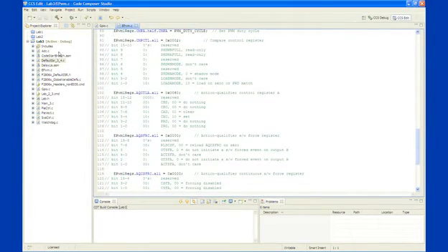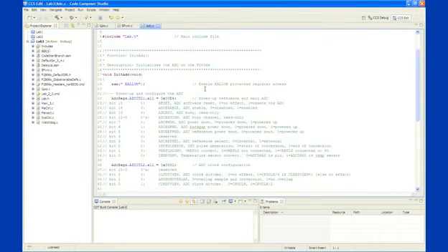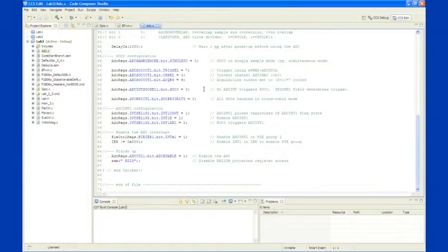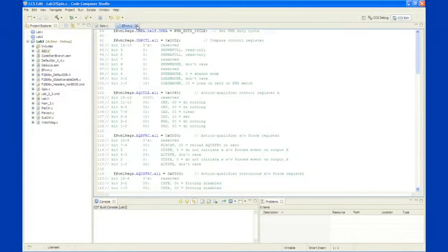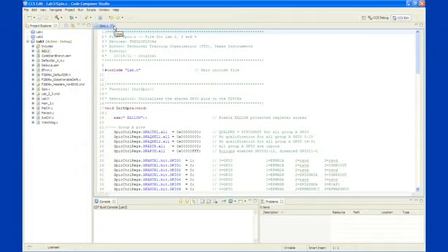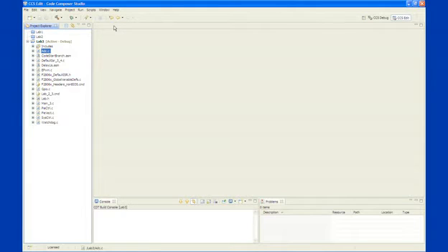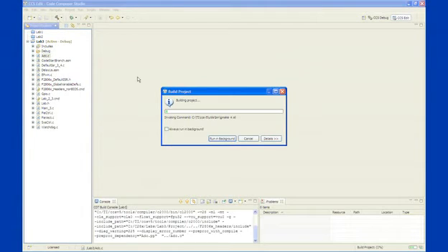And we'll take a look at the ADC.c file as well. Here we're setting up the ADC, and down here we're taking care of enabling it for interrupts. Here's the 1.1 piece right here, and it's coming off of core interrupt line 1 as well. And we understand now the GPIO pin is configured, so we have an output coming out on that pin for EPWM1A. Next, we're going to build it, making sure everything builds properly and we don't have any problems in the problems window.